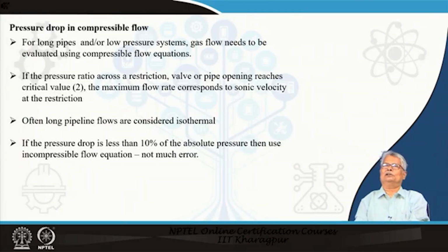Now, we have talked about the compressors. We will know about it in more detail after this. Compressors are basically to overcome the pressure drop which is going to happen when I have a compressible fluid circuit, which could be an air circuit, it could be a vapor or a gas circuit, and there is naturally a pressure drop associated with it, and this pressure drop has to be overcome, and for that we use compressors.